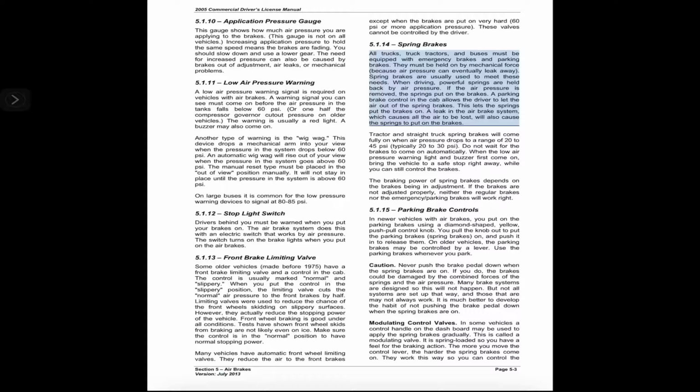Spring brakes. All trucks, truck tractors, and buses must be equipped with emergency brakes and parking brakes. They must be held on by mechanical force, because air pressure can eventually leak away. Spring brakes are usually used to meet these needs.